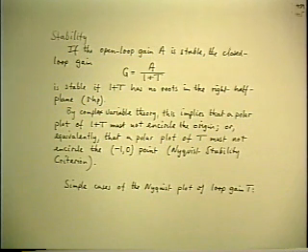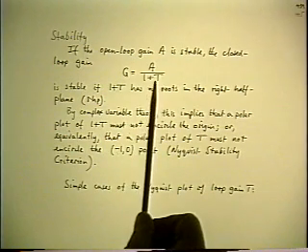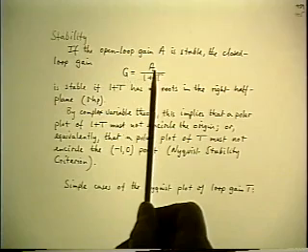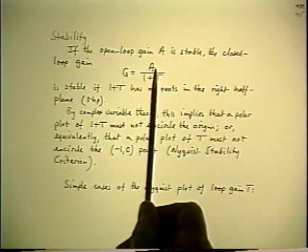For example, even inside each transistor, that collector-base capacitance is in a feedback position. And there may be other internal feedback loops that are unintentional, but you're stuck with them anyway. So, in fact, it does require a separate independent assumption that the open loop amplifier itself is stable.